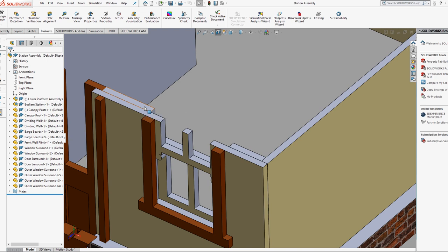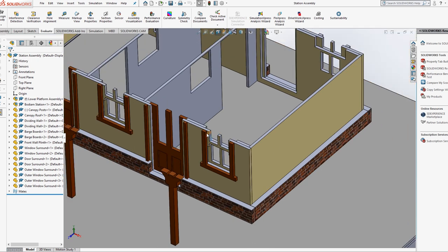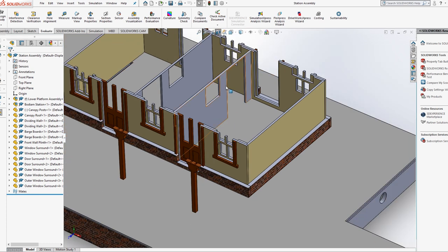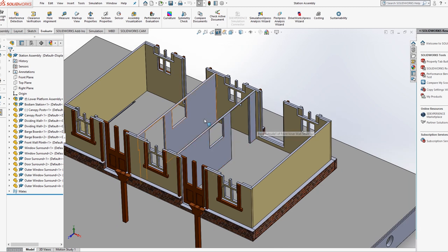And they're slightly different in all sorts of different ways. For example, when they're glued together, they allow for this rebate, which allows the end wall to glue in. There's also some details of the windows that we'll show. We can see how the window frames are a separate piece that's cut out and stuck on. If we have a look, for example, at this dividing wall, if I hover over it, you can see that if you follow this orange line round, it's actually notched into a little housing that's allowed for in the inner wall skin, and you'll see on the model how those walls are removable